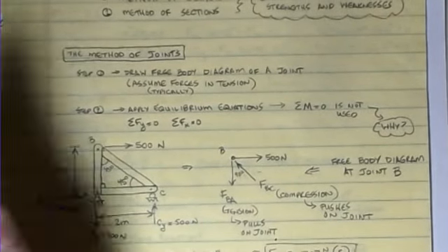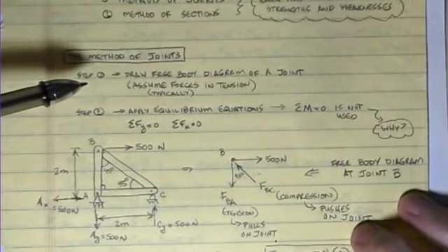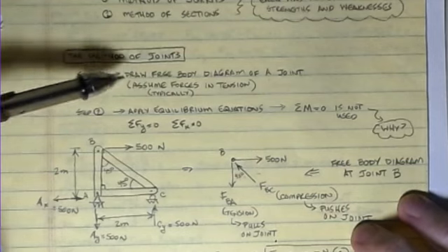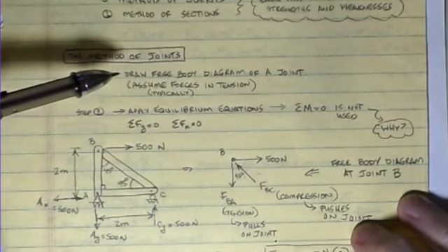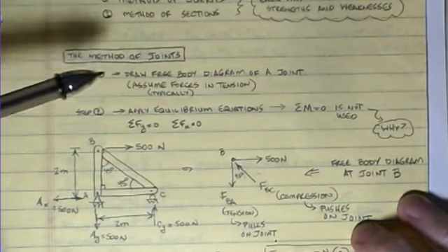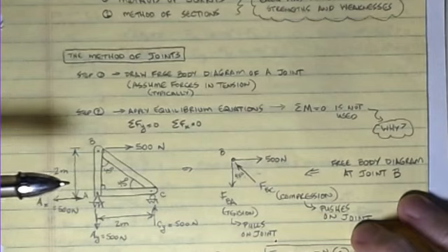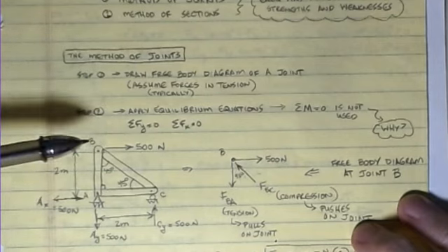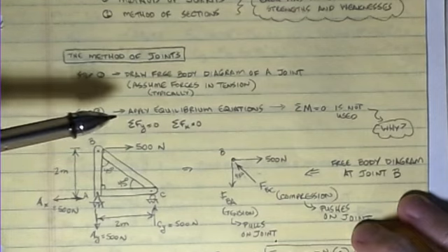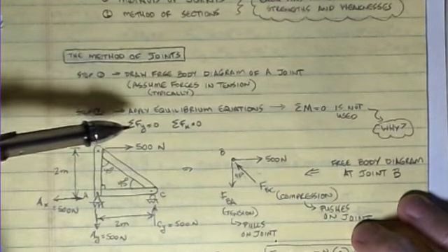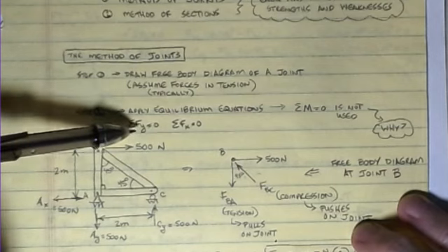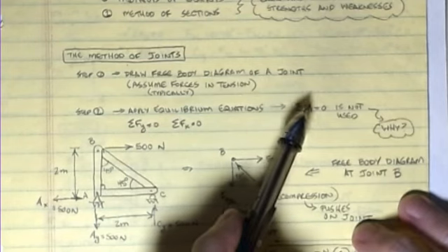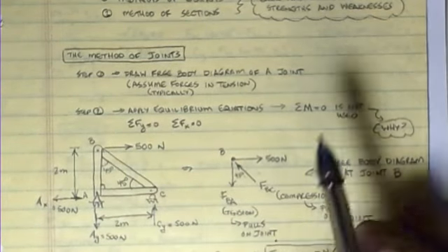Basically, as always, the first step is drawing a free body diagram. Once you have a valid free body diagram, remember our Y's: self-weight, internal, support, and external, and the definitions that go with that. Then, no surprise, we start to write our equations: sum of forces y, sum of forces x, and then I also get the sum of moments, which is not basically used, and I'll explain why in just a second.